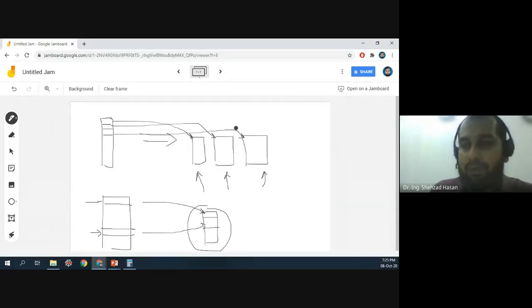We have talked about that early. This is called memory interleaving. When you store consecutive elements, you store them in different banks. So if you are doing memory interleaving, this is going to work for consecutive elements, because these are stored in separate banks. But these are not consecutive elements in this case.